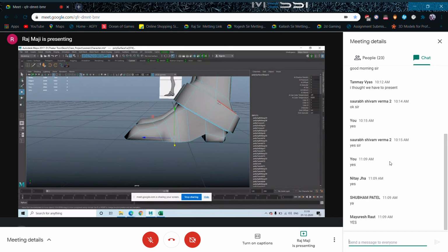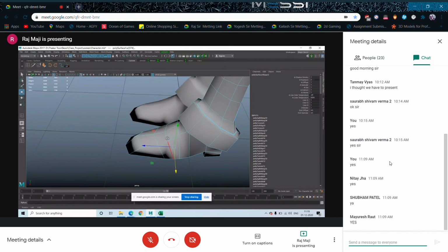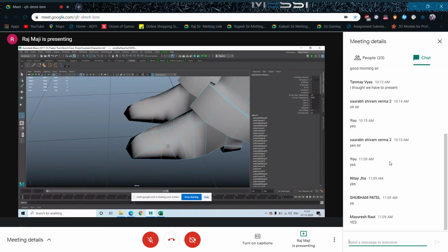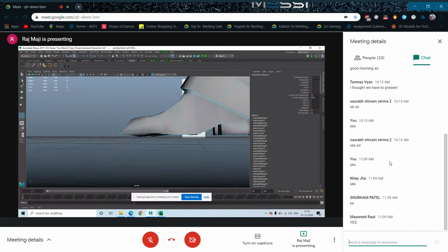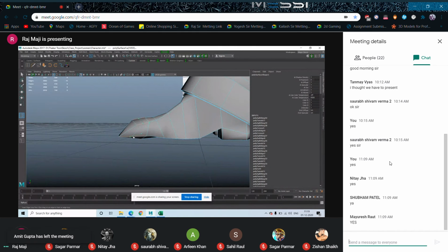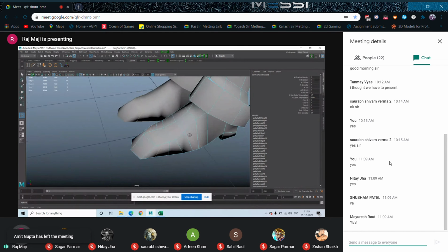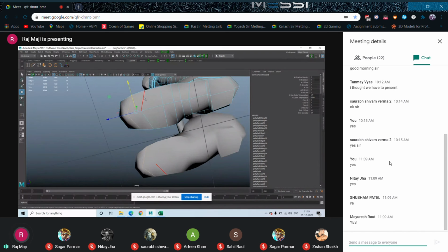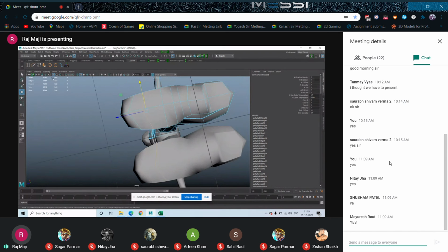So generally, if you are rigging it, we give one joint over here, from here another joint, and from here over here another joint, right? So over here also I have to add 2 more edge loops. And definitely not only for that, but it is going to hold the shape of it. That is much more important in modeling.